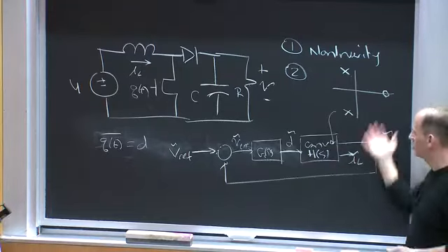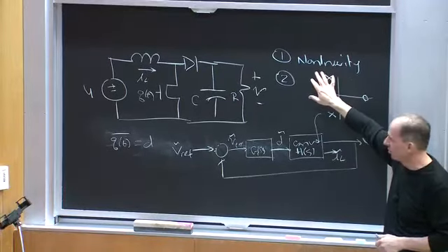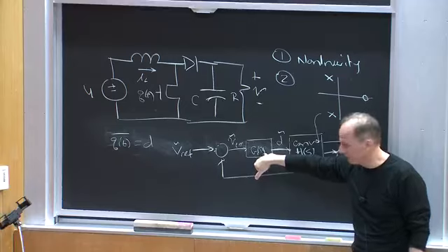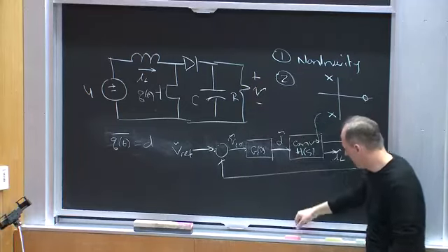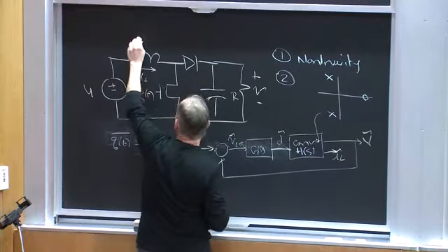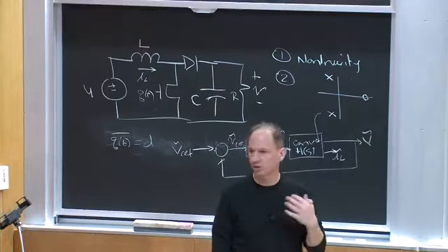We said, well, what can I do about this situation? Because this is a hard thing to deal with. You can deal with it. You can design a compensator Gc(s) that will deal with that, but it's not very pretty. One thing you can do is, by choosing L and C appropriately, that helps you set dynamics the way you'd like them. The other thing you can do is change the plant.